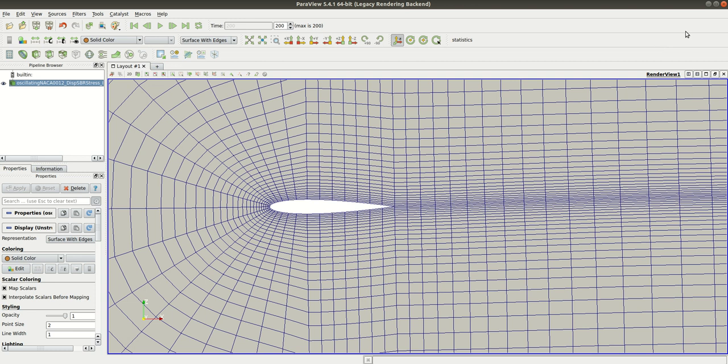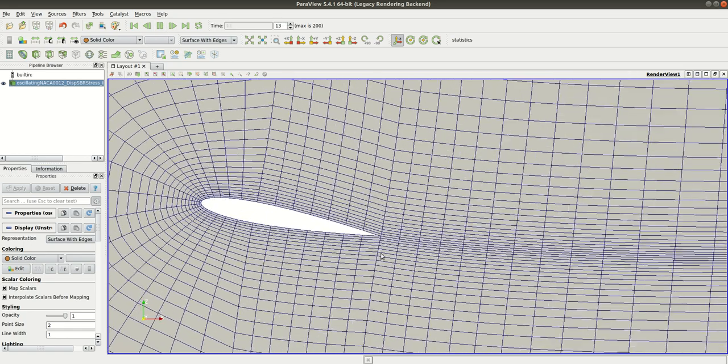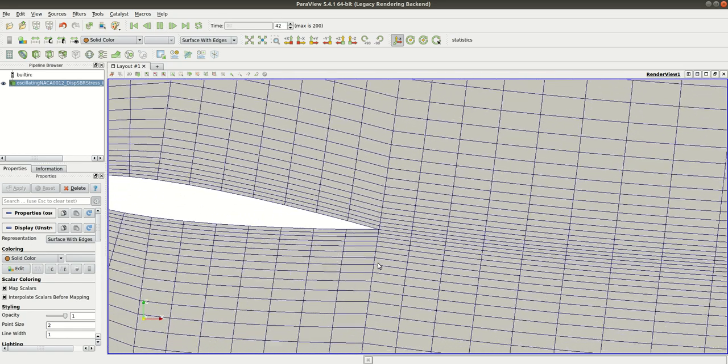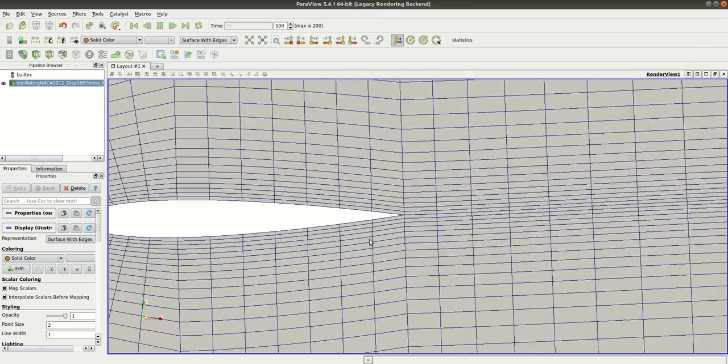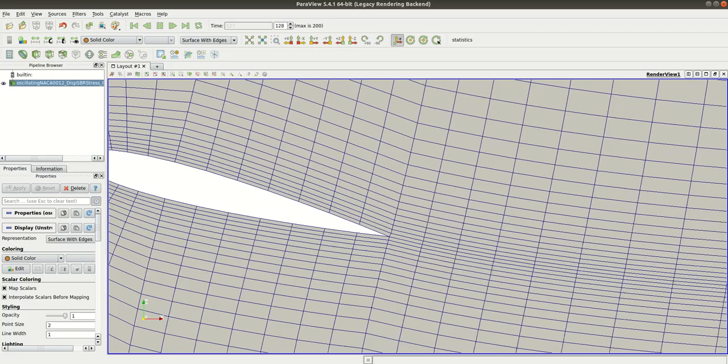With this kind of mesh motion solver, you have to really tune the parameters of the mesh motion. Every problem has its own parameters and you have to make a lot of attempts before obtaining a good mesh resolution throughout the iteration. But with some effort it's possible to do it.